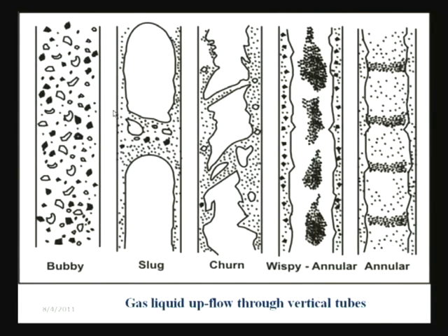Now, remember one thing, once these bubbles are formed, their shape does not change further with more introduction of air. What happens as we introduce more and more air? In this particular case, both the frequency as well as the size and the shape of the bubbles were changing in bubbly flow. In slug flow, once the bubbles have been formed, their shape does not change. If we introduce more air, the bubbles become longer and longer. But this hemispherical nose and a cylindrical tail, the axisymmetric bullet shaped shape, this remains unchanged.